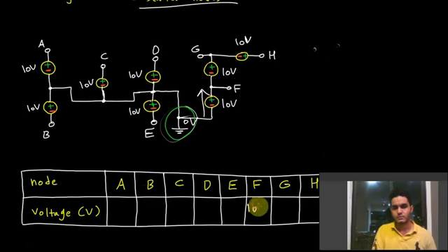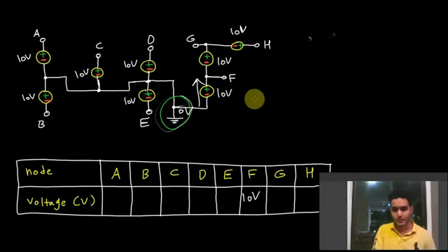10 volts. Now keep in mind that when you're measuring this, you're measuring it with a high impedance probe coming from a digital multimeter or a scope. So you're not going to be drawing current there. You're just going to be measuring the voltage. So don't worry about voltage dividers going here, if you know what that is. Now you could say that it's open. So that's the point that I was making there.